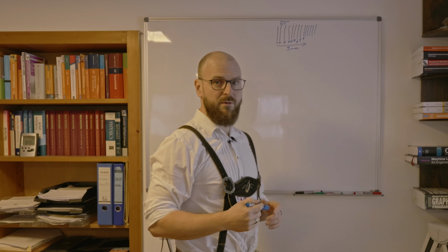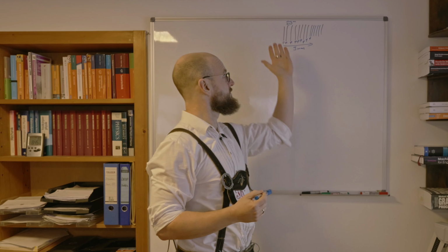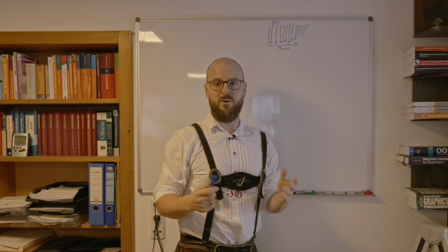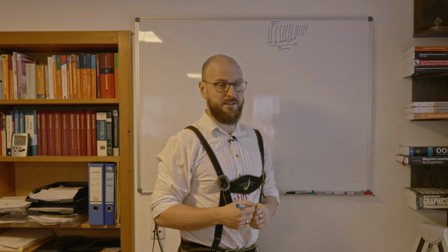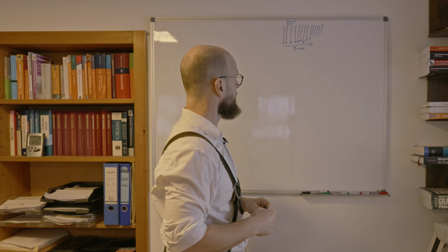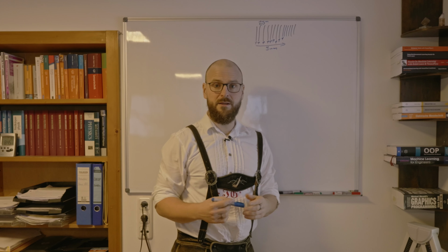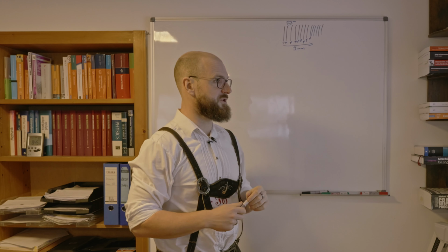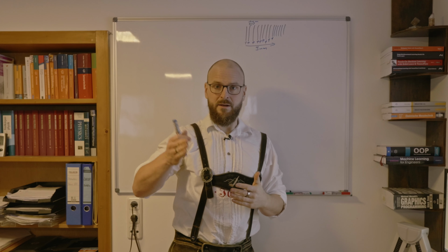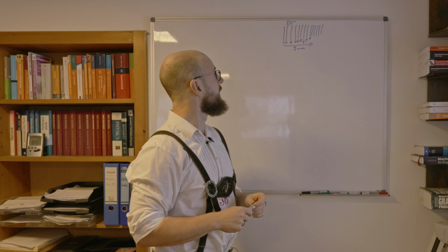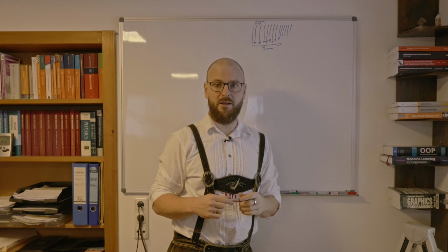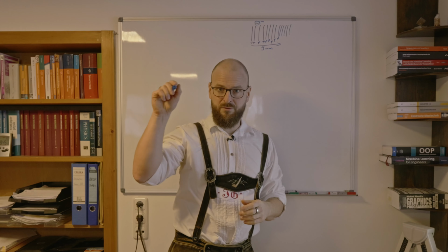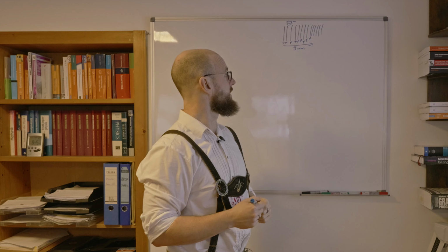And there are different ways of describing those tapes with the lines on it. One would be the optical way. Another would be using magnetism. Both are done. Optically, you can have tapes which let through light in different parts and not between the lines, for example, and by that using optical sensor technology to count the lines on the tape.